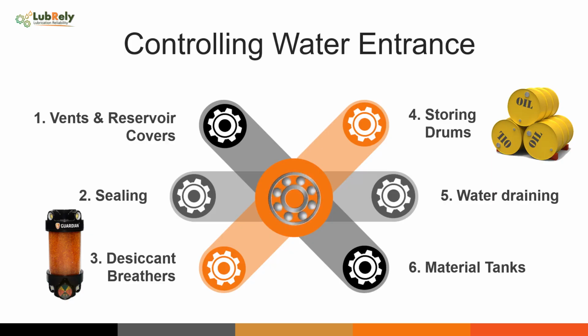5. Periodically drain water from low points in the system. 6. Environmental condensation will always occur in the tank, because of system breathing. Tanks should be stainless steel or coated with an oil-resistant paint.